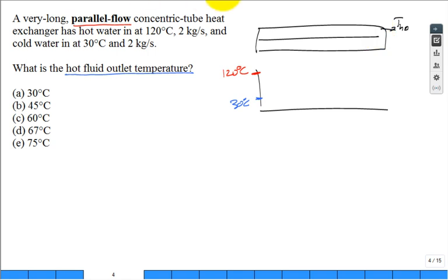The hot fluid has the same heat capacity rate as the cold fluid, doesn't it? So it's not like one is really blowing through the heat exchanger and dominating it and acting like a thermal sink. No. And so basically if the hot's changing, the cold is also changing.